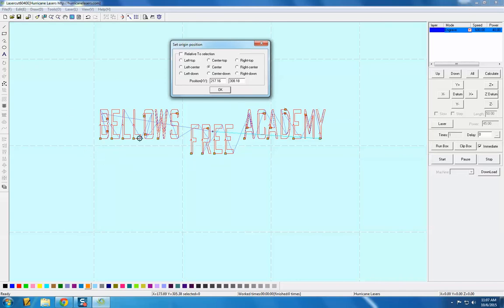I find it easy, we deal with a lot of square parts up in the shop where we can just draw an X from corner to corner on the part to locate the center, and it gives me a nice easy way to reference that.